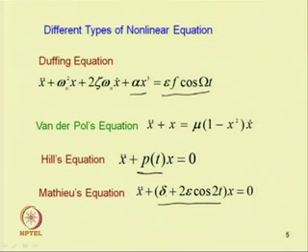For discrete systems, we have derived these equations, where you can see all of them are ordinary differential equations. But in the case of the distributed mass system or continuous system, we will find equations which are partial differential equations of motion, because the displacement, or the state vector, is a function of both space and time. So, let us first derive the equation of motion for the Euler Bernoulli beam.